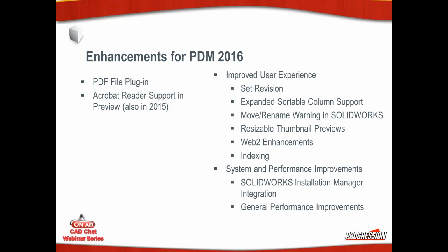The PDF files themselves have been improved and enhanced over the years with 3D PDFs and the ability to have fields in the PDF. Having this PDF file plugin within ePDM, again PDM Professional, we now have the ability to fill in those fields by writing custom properties to the PDF file, something we haven't had available to us in the past. So we can map those custom properties to the data cards and so on. I think that'll benefit quite a few folks who use PDFs for filling in information and forms within their organizations.